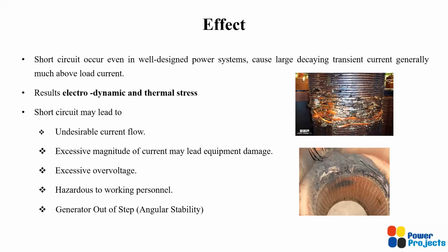So the short circuit may lead to an undesirable current flow, a current flow which is not really desired for the system. It's excessive in magnitude, and it results in equipment damage thermally. And sometimes this short circuit may result in over voltage also. Few people may get a surprise as to why there is an over voltage.